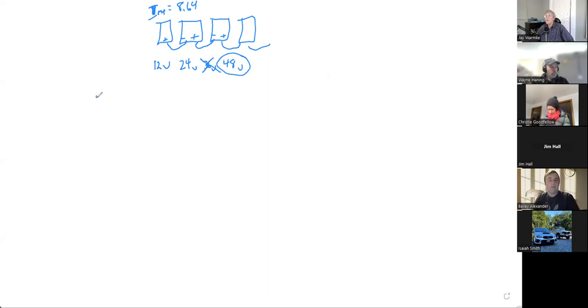So if I had a solar array where it was like here, the first thing we're going to go to is your combiner box. And from the combiner box, we're going to go to a DC disconnect. And from the DC disconnect, normally they're attached. This is going to be our inverter.